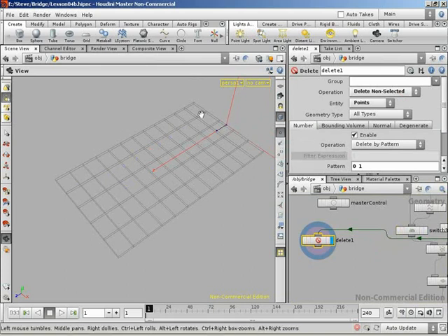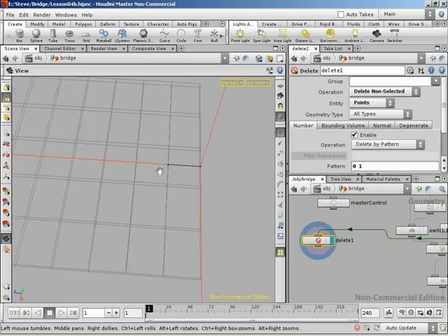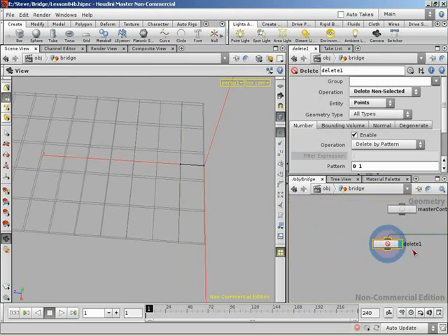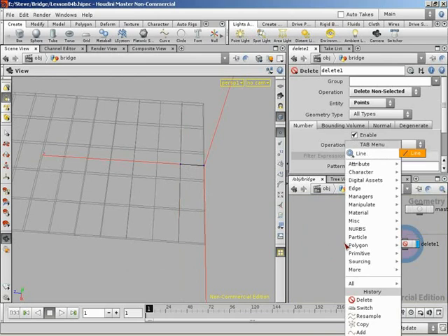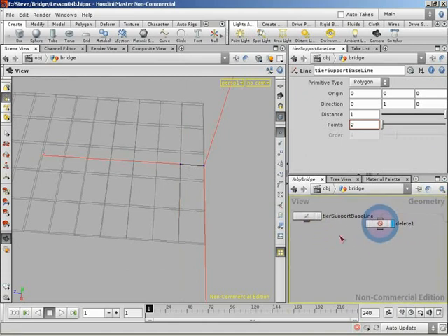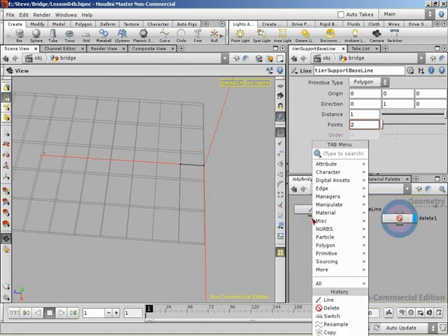Which gives us just one line segment that is the correct width for what we wanted to deal with. So we can now create a new line and set its translate Z positions based on these 2 points. So let's drop in a new line. I'm actually going to leave it at default settings. I will rename this guy to, I'm thinking tierSupport baseline maybe. Okay. And we can wire this into a new point SOP.